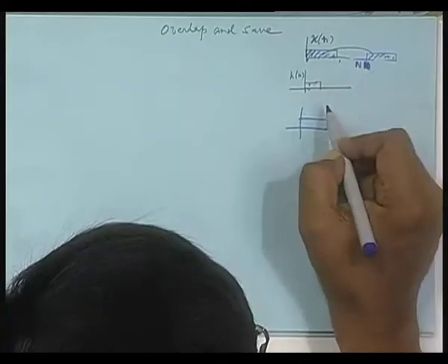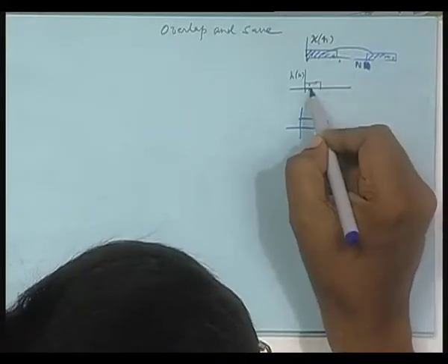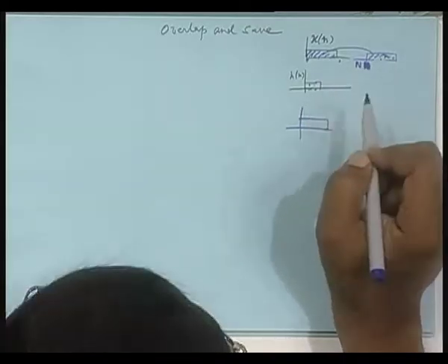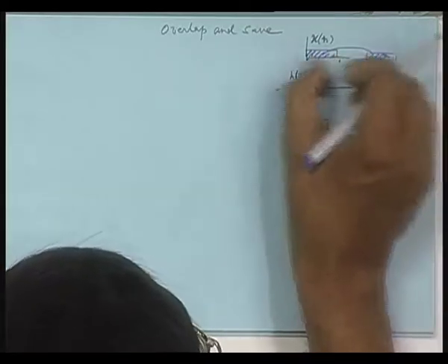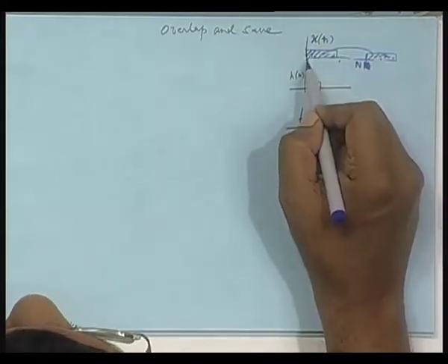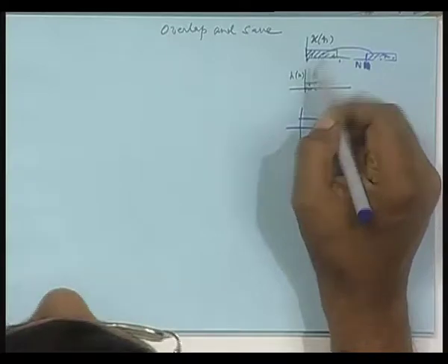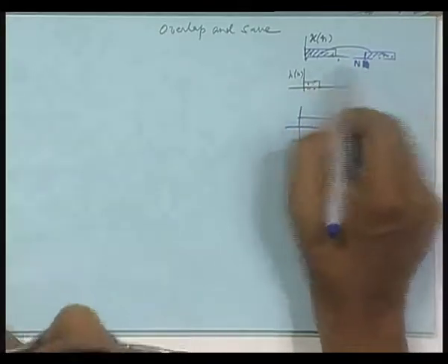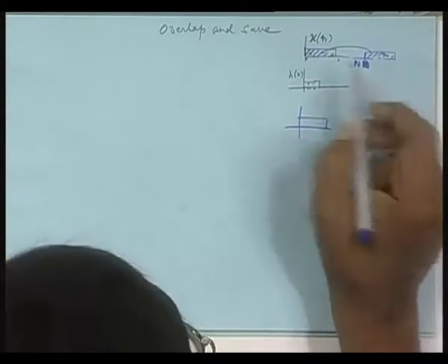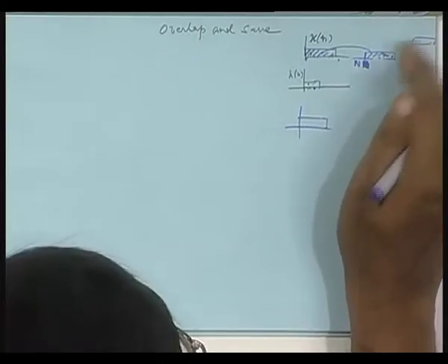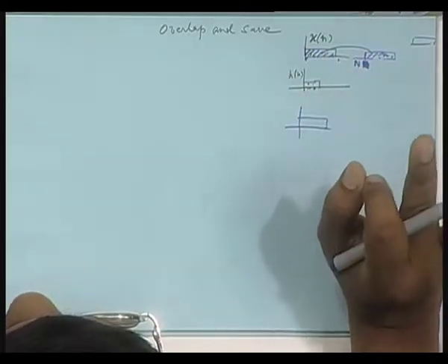Okay. So, conversely, if I am convolving two sequences which are separated like this, then I can make life simpler by simply shifting it, aligning this with origin. Convolve, calculate the output, and again shift it back by capital N. So, next time I can convolve with some other segment here. I will again shift it back to origin, convolve, get the result, and again place the output there. This way I can do.